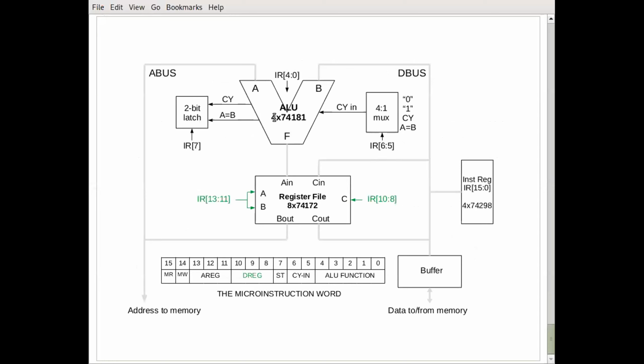Now, I talked about a tweak I wanted to make. Why I'm not entirely satisfied with that. It occurred to me after wire wrapping this prototype, and it's a lot of wire wrapping, that rather than forcing all memory operations to go through register 0, I could make the data register, and that's deceptive because they're all address and data registers. This is not like a 68,000 where you have different functions. This is a PDP-11. Any register can be used for an address or data. But the register on the D bus is how you should read data reg or DREG.